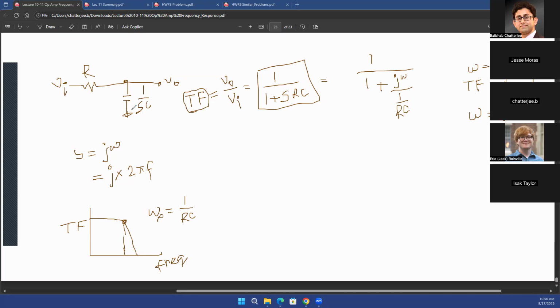So as we discussed earlier, impedance is just frequency-dependent resistance. So for a capacitor, you see this frequency dependence, because the impedance is 1 upon SC: at 0 frequency, the capacitor is an open, at infinite frequency, the capacitor is a short.